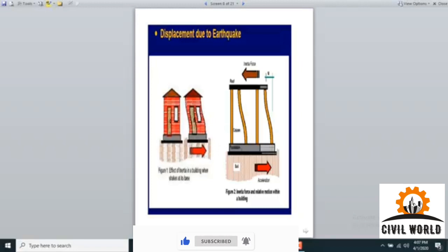This story shear is resolved like this. If you remember Newton's second law of motion, it is an inertia force. If there is an action, then there should be a reaction. Based on that law, if there is some impact on the base of the structure, it will result in drifting the upper side, known as the superstructure, in the opposite direction. So the wave will be traveling in the forward direction, and the upper part of the structure will be traveling in the backward direction. And this is where structures normally collapse or fail. The collapse or failure of the structure normally takes place at the joints.